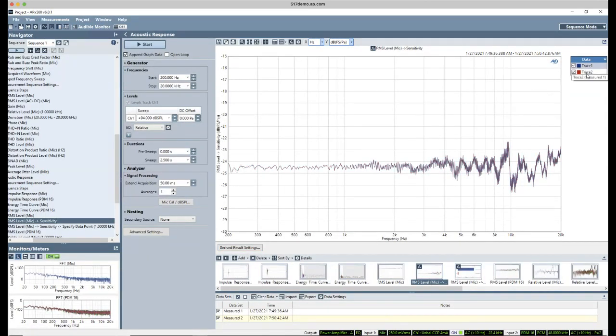So you can see that they actually land right on top of each other. And that's actually maybe one of the biggest advantages of using what I will call the simultaneous mic substitution measurement technique, of using a reference microphone positioned near the microphone under test, is that one of the things this does is gives you quite a bit more flexibility in the source speaker that you use for your tests, because that speaker doesn't have to have a perfectly flat output.